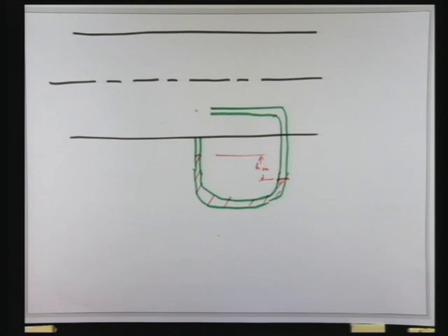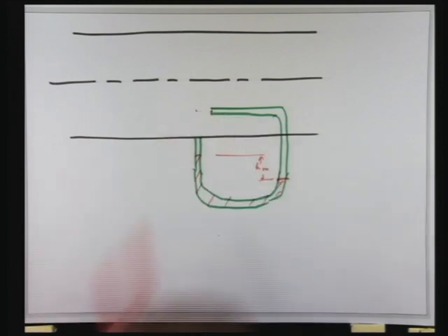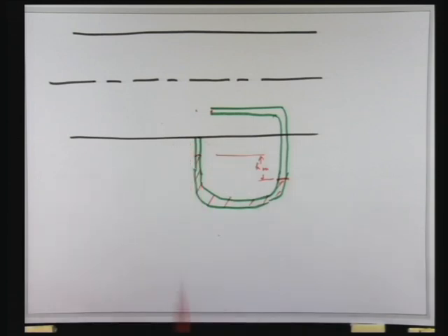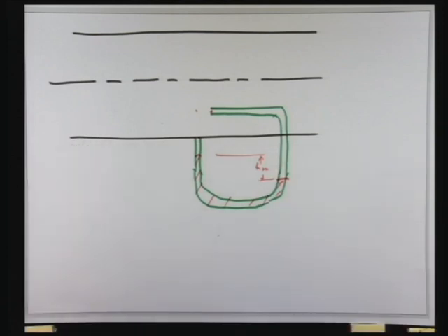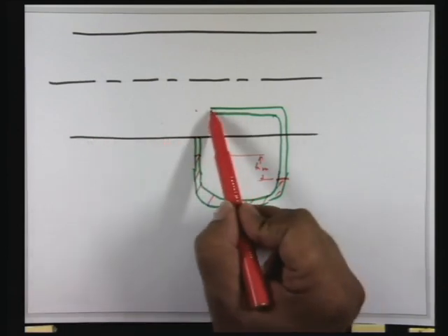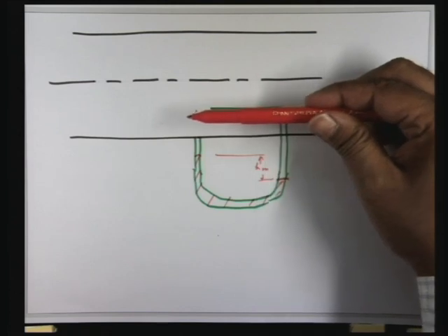No, no. See, the pressure at this point is not stagnation pressure. Can you explain why? If you look at viscous flow, the velocity is 0 along the plate, but those are not stagnation points. The concept of stagnation point is coming from inviscid flow. And if you have an inviscid flow, it will slip along this wall. But here it cannot, it is obstructing the flow. It is in the opposite direction.